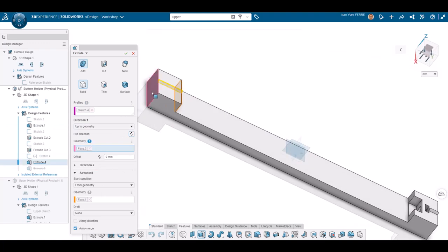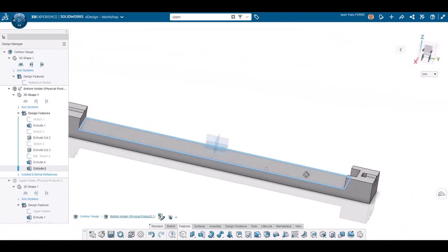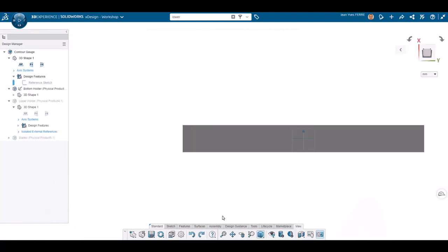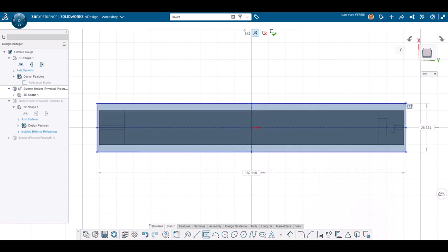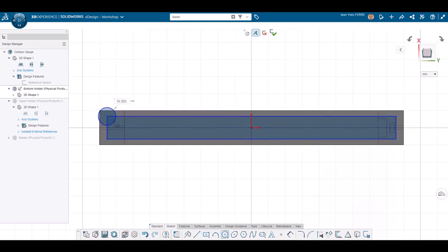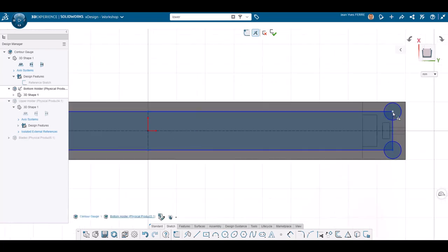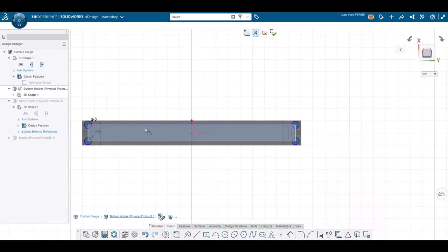To create mounting holes, I change the display to see edges through the parts. So I create holes where I'm sure there is some material. You must admit, it would be a shame to drill into my marvelous clamping system. Just kidding. To make sure holes are balanced correctly, I use a centered rectangle to drive holes symmetrically and I start with head clearance holes. Of course, I measured the bolt head to add the right dimension and of course with an offset, so the bolt moves freely.